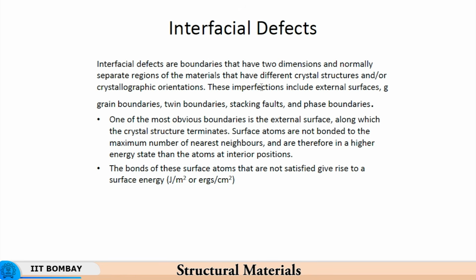So when we said that you have carbon dissolved in iron to form ferrite, then you have this α phase where you have a body centered cubic crystal structure with interstitial carbon atoms dissolved in iron to the extent of 0.02%, whereas you have cementite, which is another phase where the crystal structure is different as compared to the body centered cubic of iron.